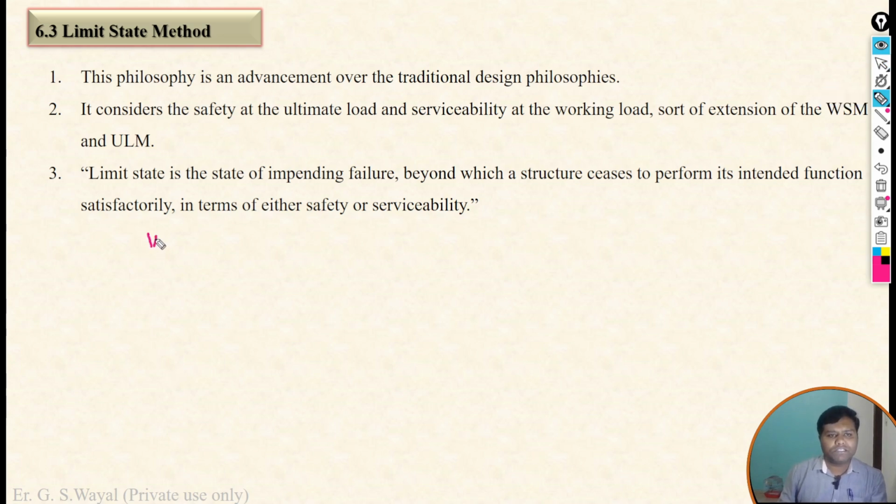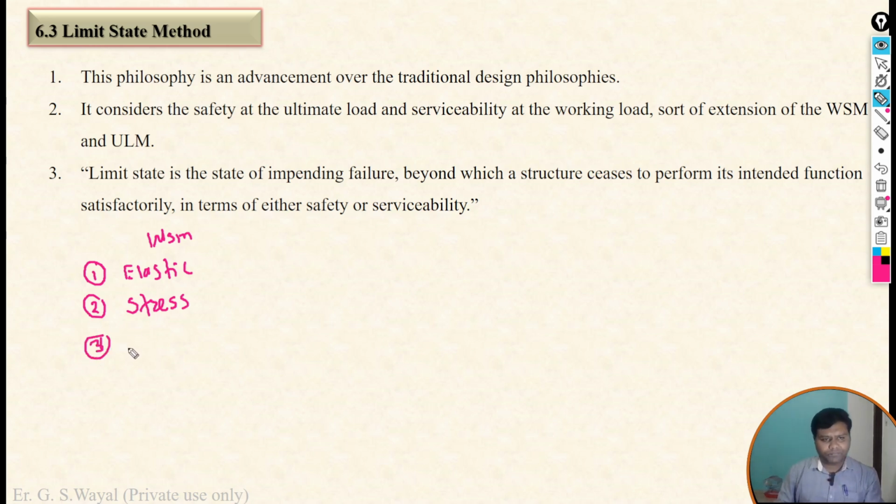If we consider the working stress method, I'm just giving the important points. In the working stress method, we are considering only the elastic region. Second, we are using the stresses for the design point of view, and then we will get higher sizes. That is how the working stress method works.